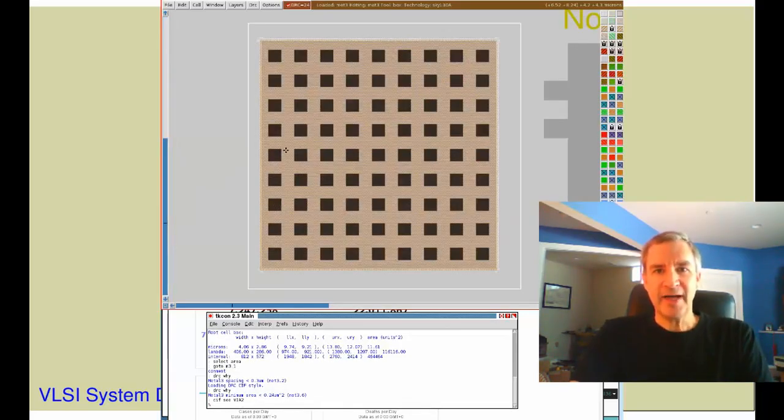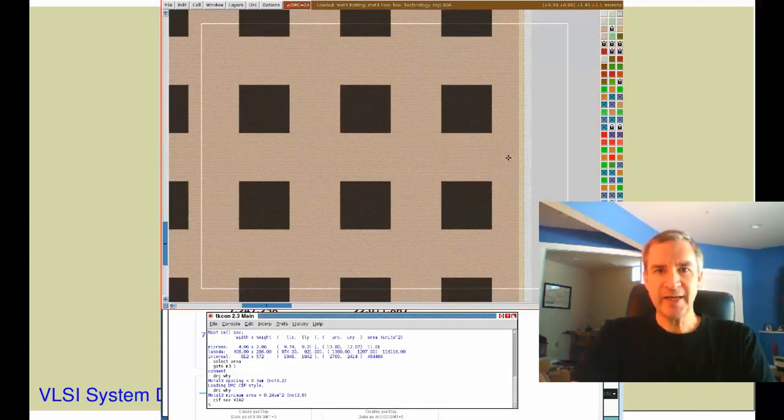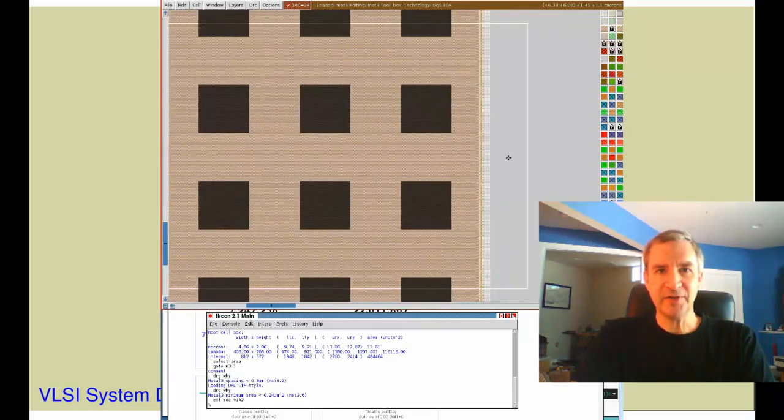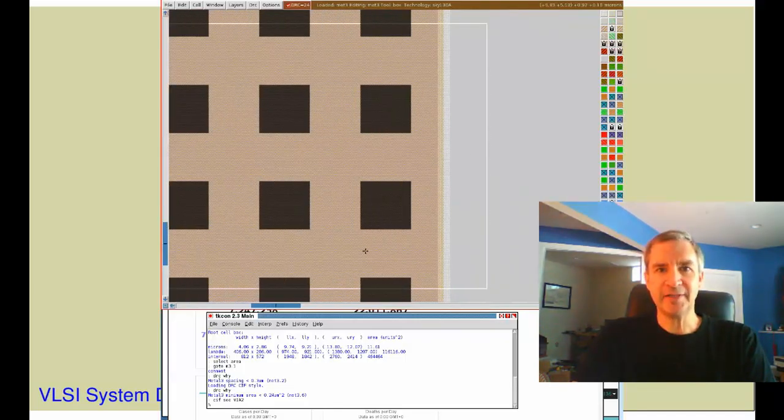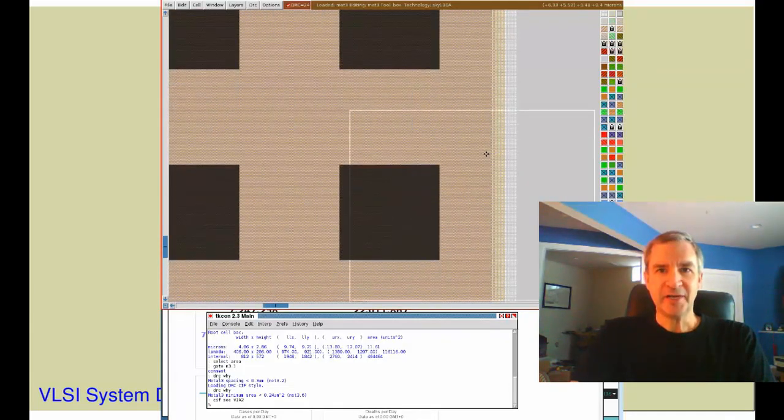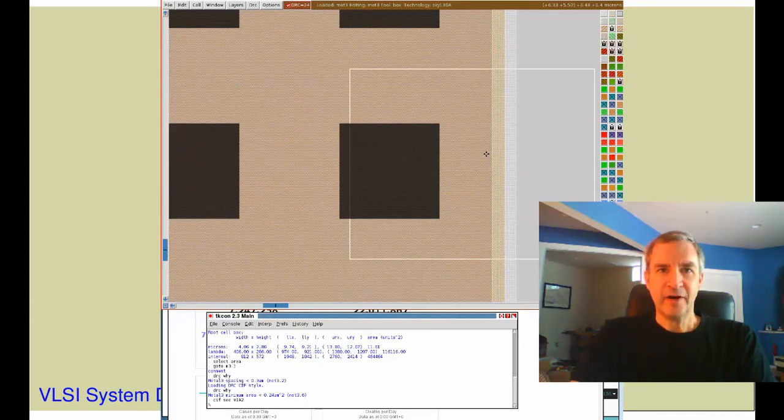These are the contact cuts, and they don't actually exist in the drawn layout view. What they represent is the mask layer for VIA 2 that will end up in the output GDS when you generate GDS from the layout. They are created from rules in the CIF output section of the tech file, which has a special command for telling Magic how to draw contact cuts inside a drawn contact area.